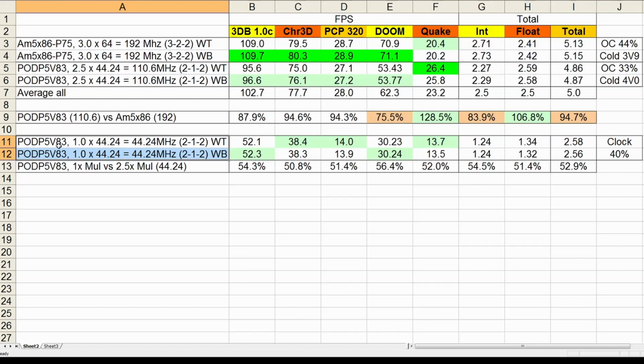The one is that just the bus interface of the Pentium Overdrive cannot run at these high frequencies. And the other is that there is probably an internal PLL in the Pentium Overdrive. There is a good chance that the input of this PLL cannot be set too high, and maybe the PLL there is optimized for 25 MHz when you have the 63 model and 33 MHz for the 83 one. So the conclusion here is that the 1x mode cannot help us break any performance records. And also, fortunately, the multiplier cannot be set at any other setting.